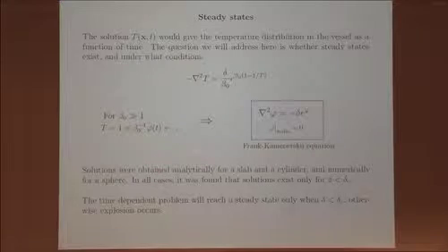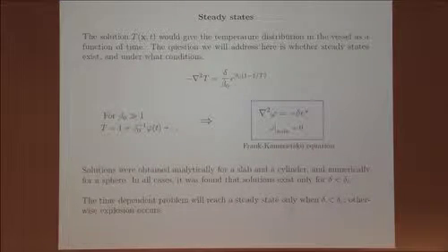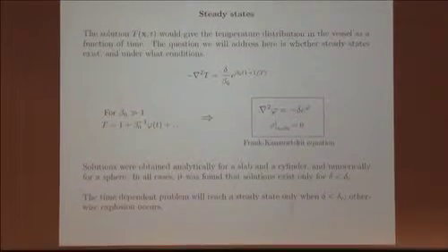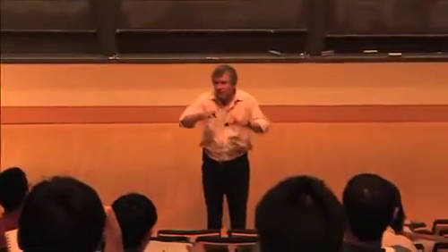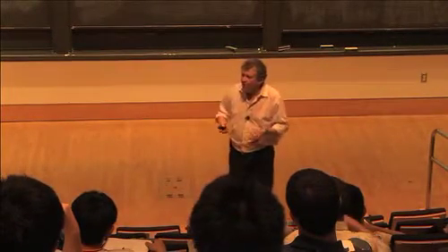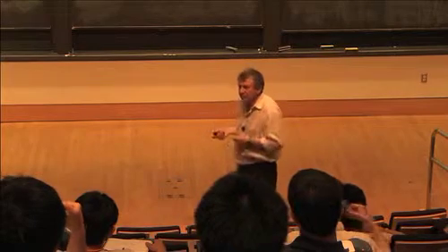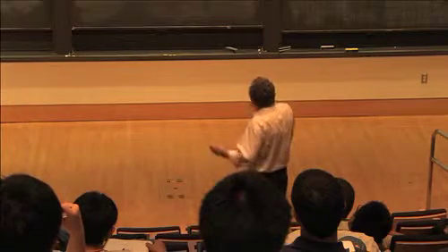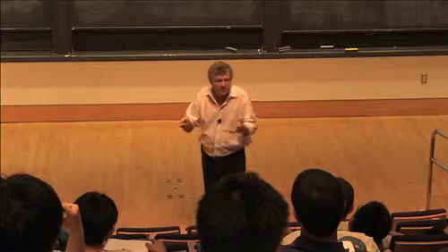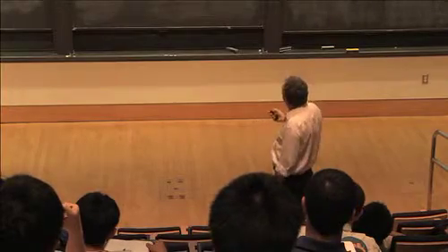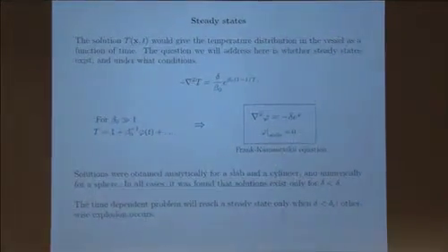And so, the typical problems that have been solved in the literature are either a slab, which is in Cartesian form, a cylinder, which is in cylindrical coordinates, or a sphere, which is in spherical coordinates. Other configurations are complicated, and so you have to define the boundary and so on, which is of course not standard, and so that's not found in general. And if that's your interest, then it's possible to do it, but you have to solve it numerically according to the geometry that you have. Now, the first two, the slab and the cylinder, turn out to be solvable almost analytically.